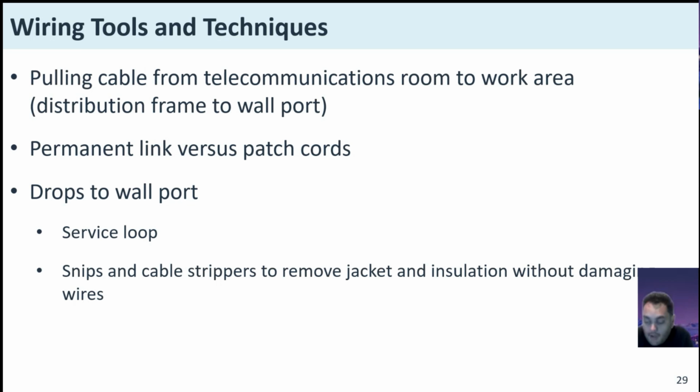Now remember, I've seen a lot of people that strip a cable and they're like, oh, well, the orange wire, you could barely see the copper in it. Well, great. Cut that and restrip it and rerun it. If you see any break in that wire, that's going to cause issues. Just make sure that those wires are clean and that they're still shielded when you're terminating them and crimping them.